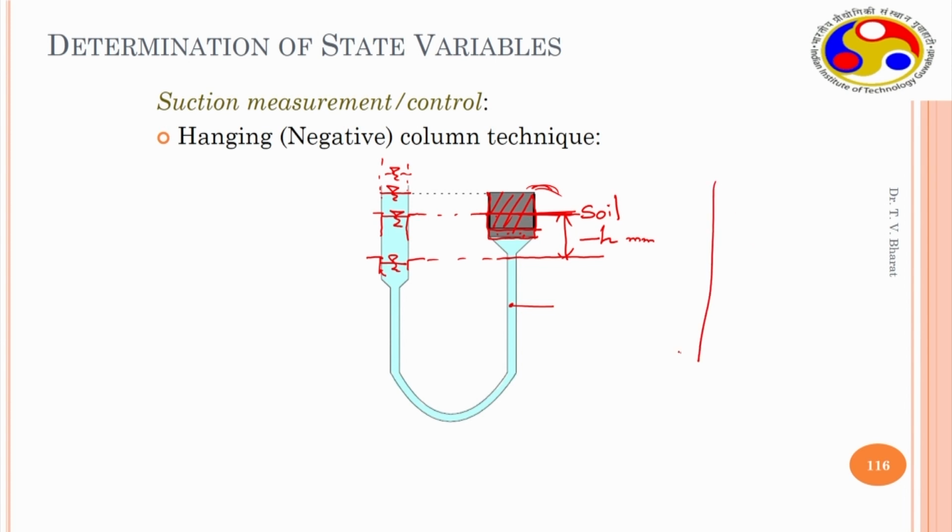So, this is on a soil water characteristic curve plot. If I plot the water content, either gravimetric or volumetric water content, against negative head, or if I multiply with gamma w, this is pressure. I can represent it in terms of pressure. When negative head is 0, the water content is fully saturated. This is Ws maybe, this is the fully saturated water content.